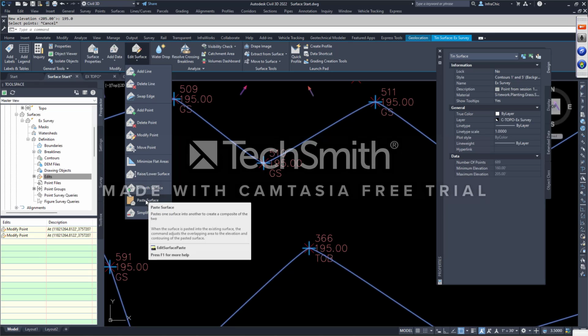Another handy one, and this usually starts off at the beginning, before you add points, is pasting of a surface. So you can take another surface and paste it into this one, and then add points from there. Anything that goes over the surface that was pasted in there will overwrite the pasting surface. This comes into play again with GIS, because I had to lower or raise my GIS. Now I need to marry the two so that when I show my sheets to my guy, he can see that it's one complete surface. There's not this 5 foot break between contours. And then I'm explaining to him what side of the surface is GIS, what side of the surface is survey.